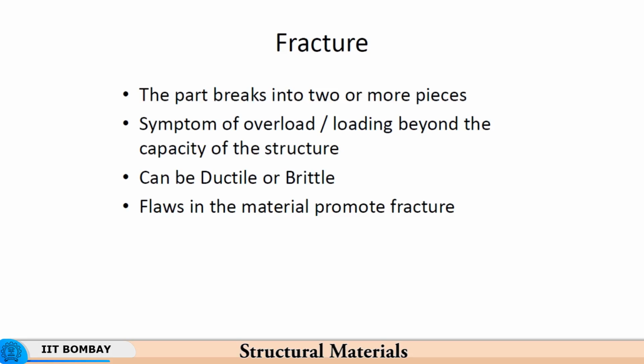So brittle fracture is an event where, prior to that, there is complete integrity of the structure, and beyond that there is no integrity of the structure at all. There is absolutely no question of the existence of a structure after the brittle fracture has taken place. This transition is all of a sudden, it happens without a warning, and until this occurs the material deforms under elastic conditions only.